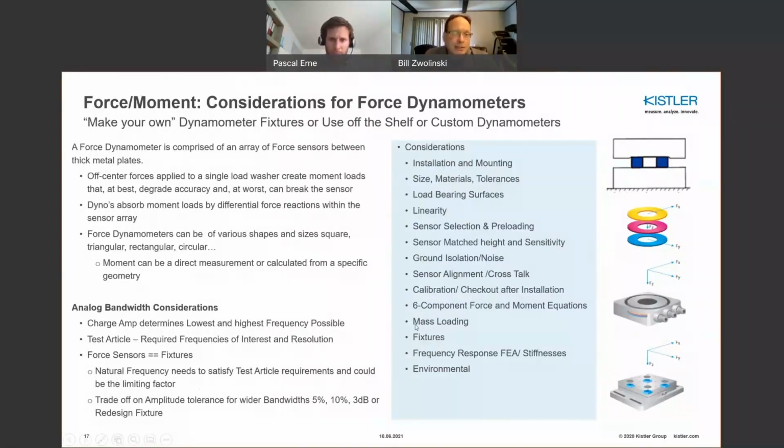Force sensors on their own really like axial loads. In a hydrodynamics application, you rarely have axial loads. So the plate itself helps distribute those forces amongst the sensors and basically absorb moment loads, so that you can make an accurate measurement when your forces are not axial.